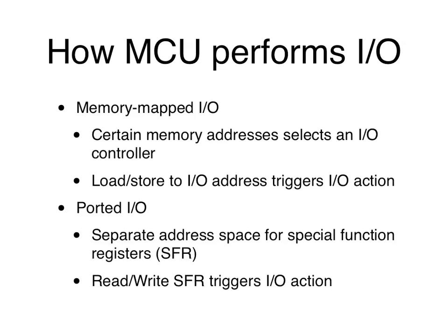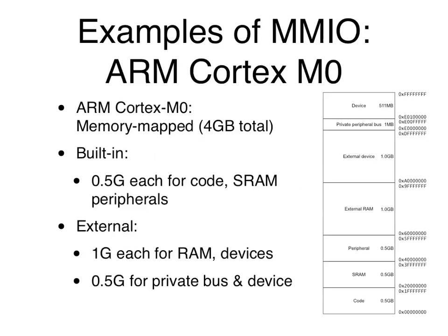To do input-output, you have a different set of instructions that access a different address space, and those addresses cause input-output to happen. Those are what's called ported I/O. And in this class, since we're using the 8051, it actually uses ported I/O. But we'll